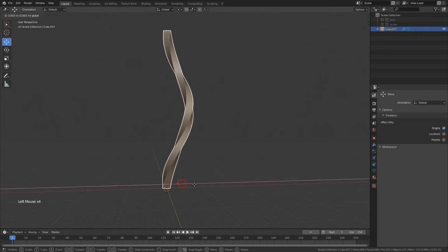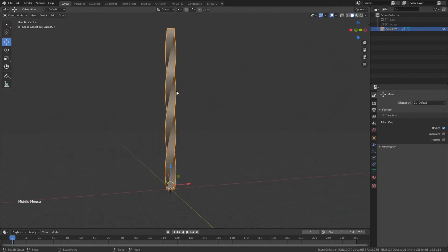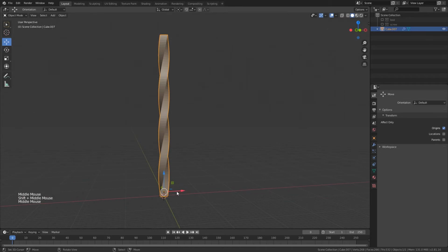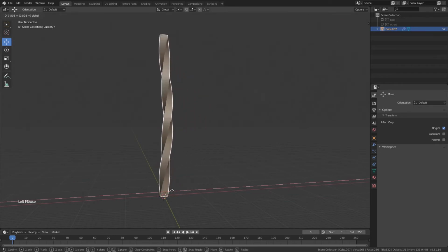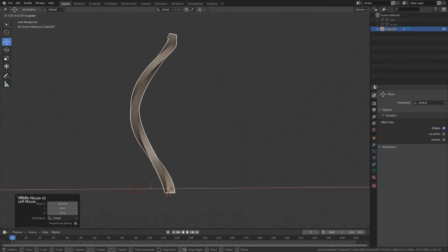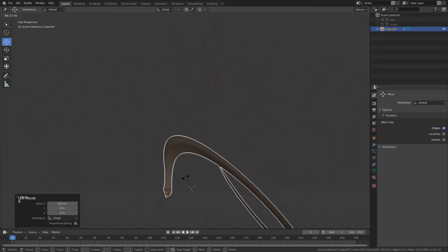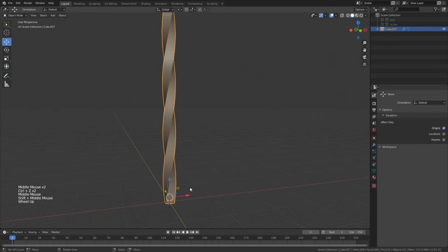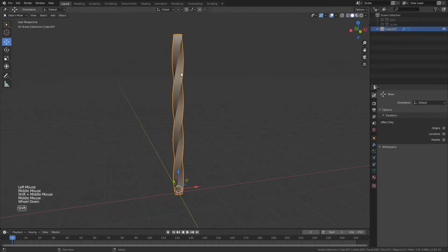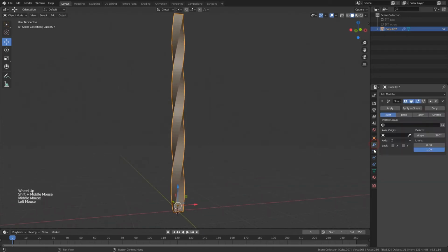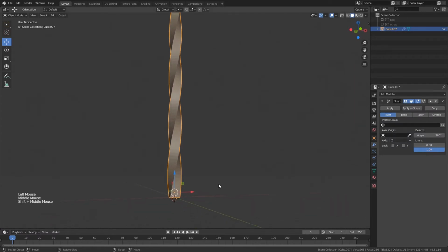active tool properties and change the origin of it, this twist modifier was taking the origin of the actual geometry. Now look at the way it behaves when I change the origin. Right now it's taking this point to deform the object, and I can even rotate this and create something very abstract. But every time it's not very convenient to actually change the origin of your object. There might be some other things linked to this object and it could break the hierarchy. Now what you can do is assign a different object as an origin.